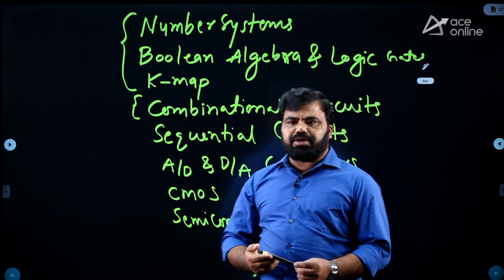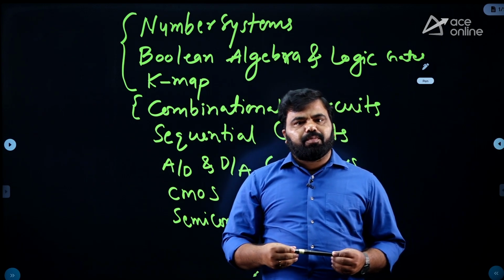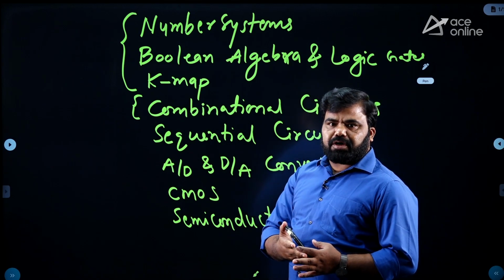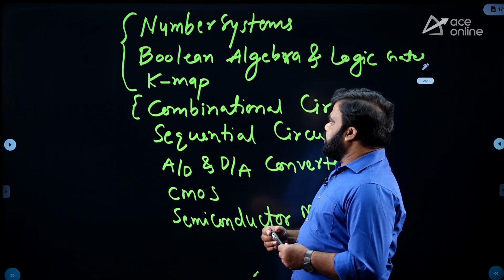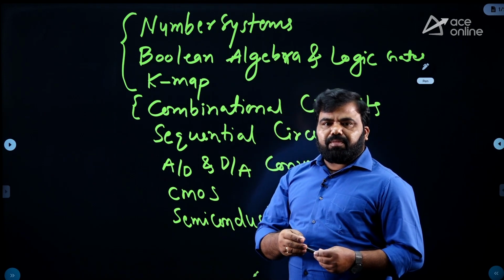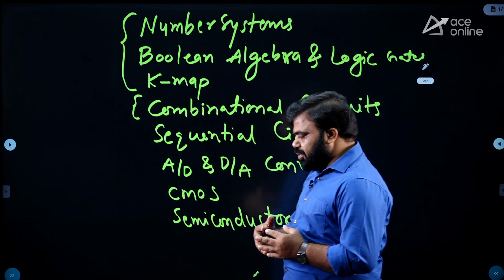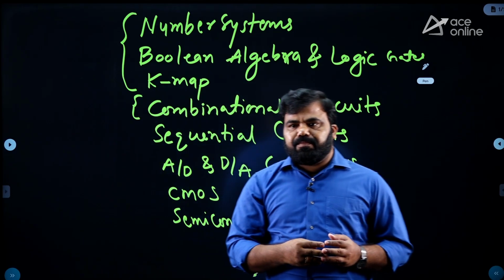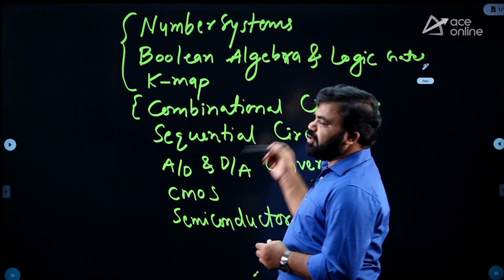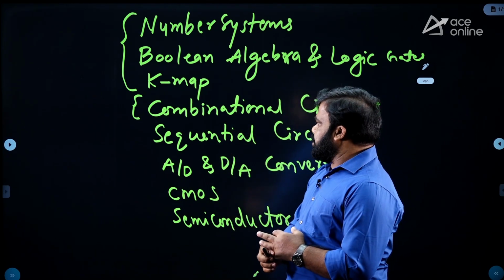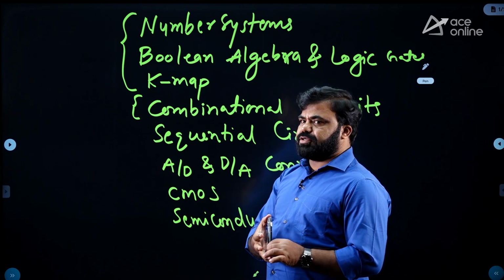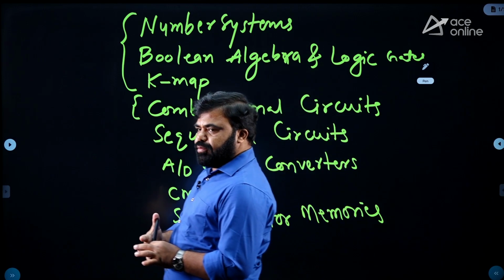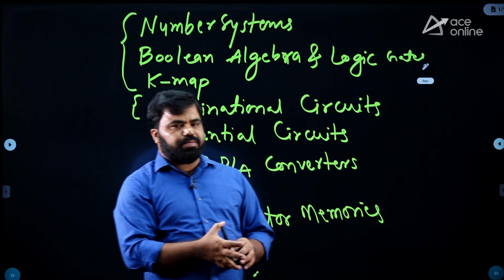In that, the most important area is adders, propagation delays of adders, and the different adders which we have, and maximum frequency of operations. Then multiplexer. The most important area from combinational is the multiplexer. Then decoder. These are the areas we have been getting questions from in combinational circuits. So one is adders, different adders, then multiplexer, then decoder. Most frequently we have been getting questions from combinational.